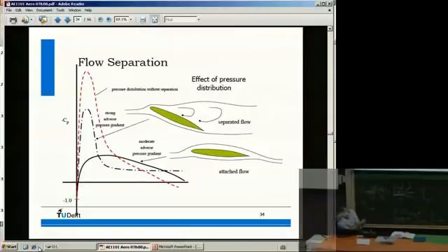If you increase the angle of attack, you get at some point separation, and then your pressure gradient drops. And this is really trailing edge separated, so you can get a really very bad pressure distribution if it's fully separated. And separation you can see in the flat pressure coefficients, pressure gradients.